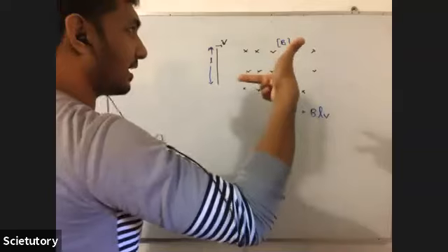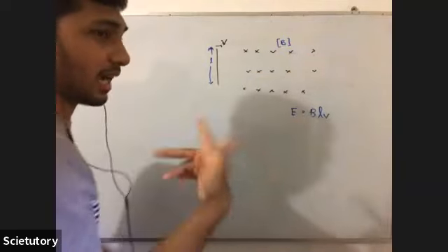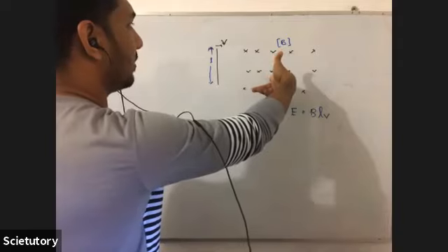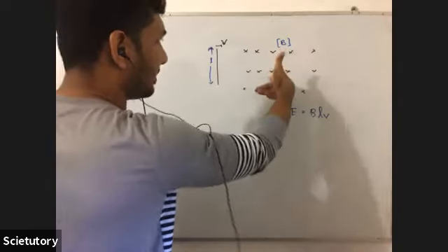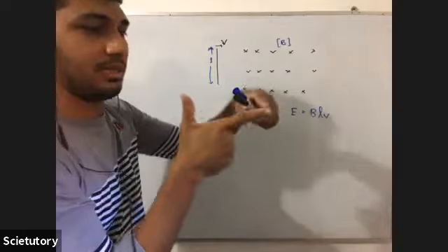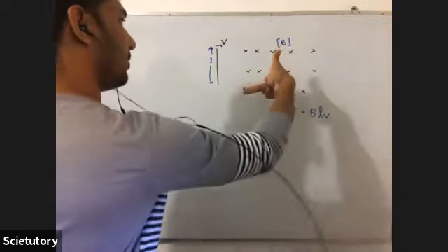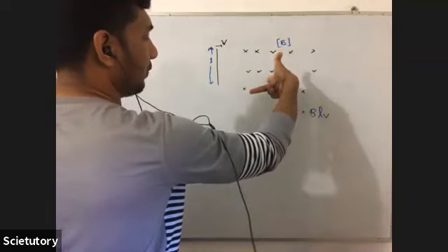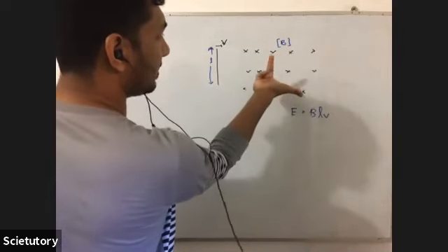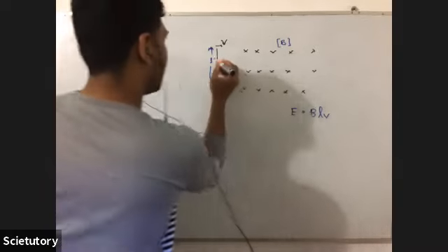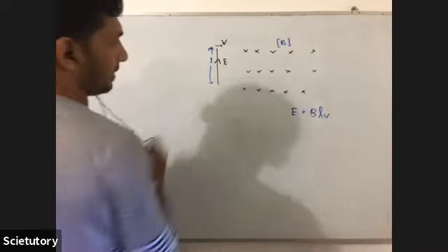Okay, this is my right hand. Make sure of that, because I have used it like that at exam time, it's very unpredictable. Do the question. So now this is movement, this is field, and this is the electromotive force. So now, with the field inwards and movement in this direction, the electromotive force is like this. So now the direction of E is like this.